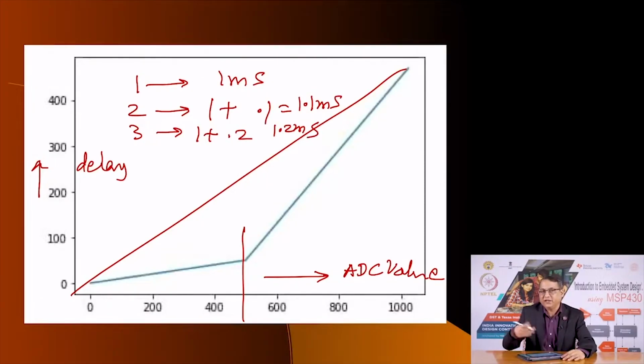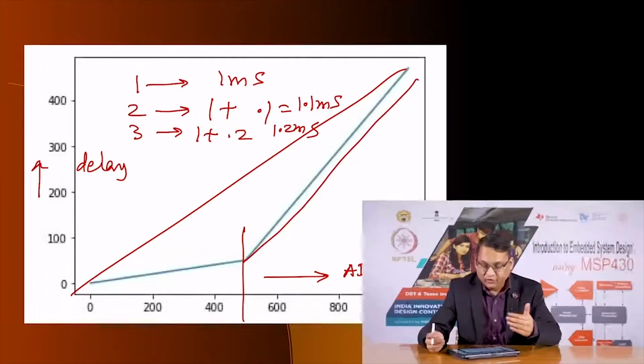The moment it becomes more than 500, we suddenly increase that percentage. Instead of 10%, we increase it to 80%, and therefore it is able to increase more rapidly. Now, if you use this, you would see that when you use the potentiometer to change the refresh rate, the refreshing of the displays changes gently from one extreme where all 4 digits are on at the same time. You can gently reduce the refreshing rate and start seeing individual digits. You will first see flicker, then the flicker will increase, and then you will see each digit being turned on one after the other.